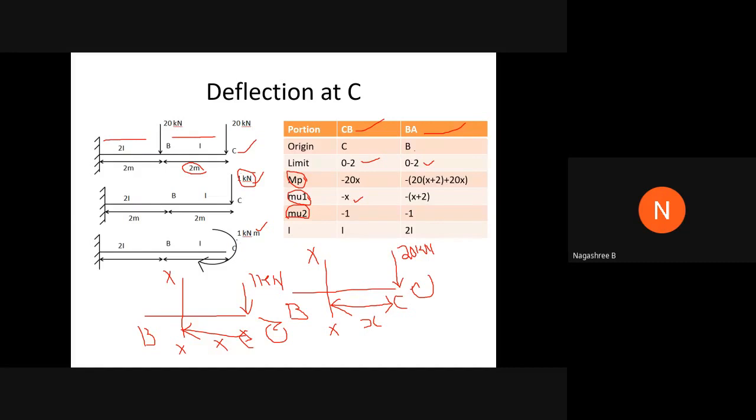So I have assumed the unit rotation, of magnitude 1 kilonewton meter, in the clockwise direction itself. Since the external moment is in the clockwise direction, we take the direct value of that magnitude in terms of the respective sign convention. So it is equal to minus 1.